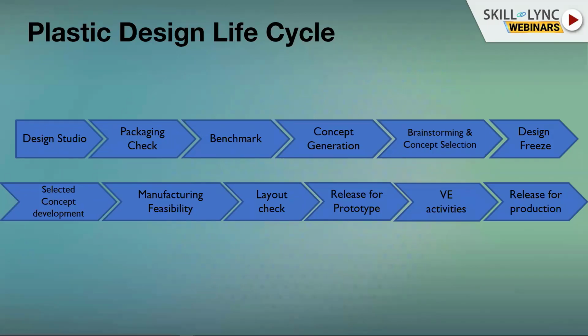They will check its feasibility, and then also there will be a part split, because once you get a design studio surface, it will be a complete surface without the part split. And then we as engineers should define those part splits and then generate a bill of materials, and then how the part split has to be done and how the attachment concept is, and everything will be done using benchmarking.